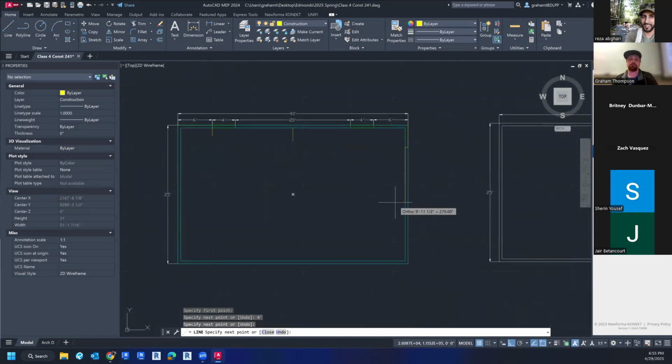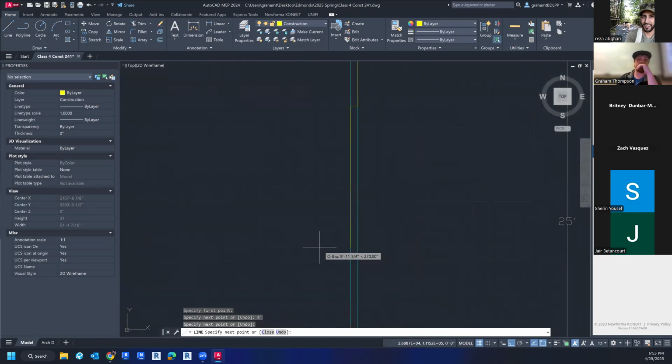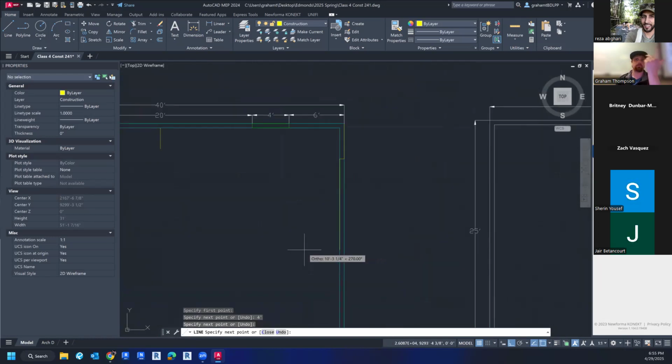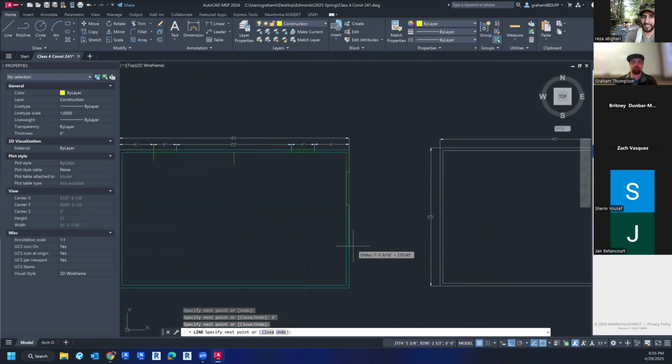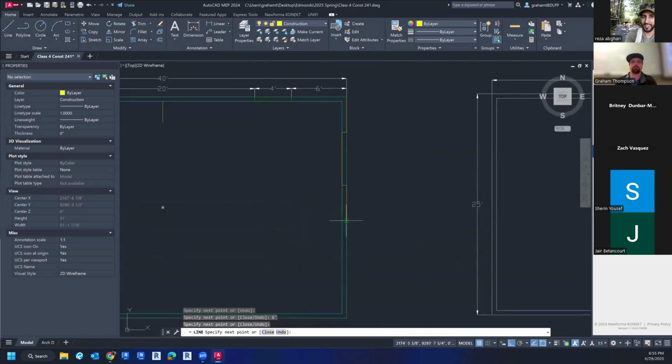And then maybe, and that's the cool thing about construction lines. It's still into drawing the next one. So if I made this cross here, right, I can draw my next one at 6 feet. And I could just keep going, right? And so when I come to actually draw my windows later, I have these locations of my endpoints. All right, let's go ahead and draw 3 feet down. And then let's make like a big old 8-foot window here.